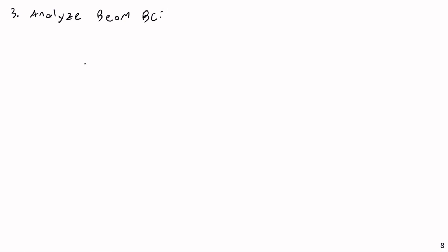So let's consider this. I'm going to cut again at distance x from the left. Distance x from the left, that's not going to change. Again, I'm still keeping my origin constant. I need to use the same origin and direction that I did for my real moment, the moment from the real load.